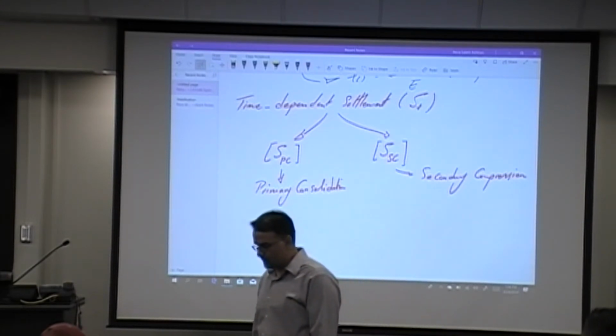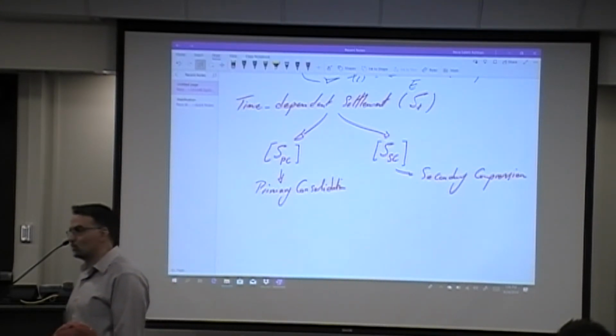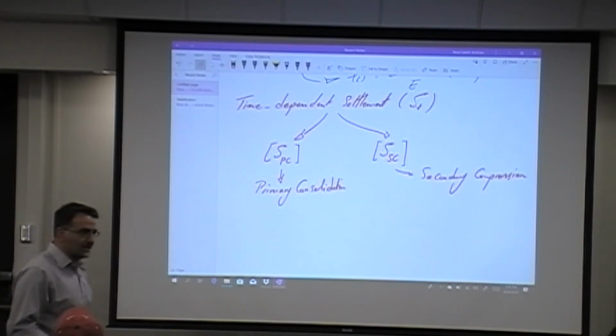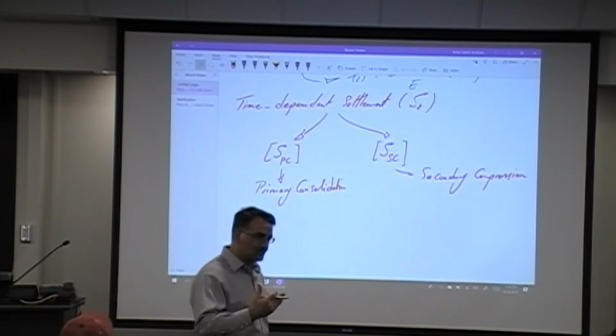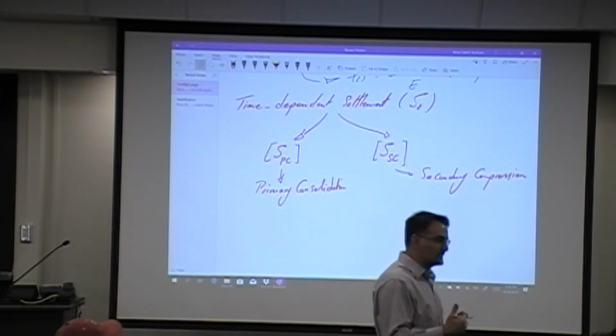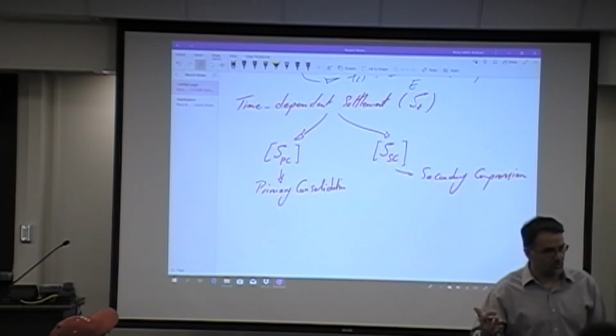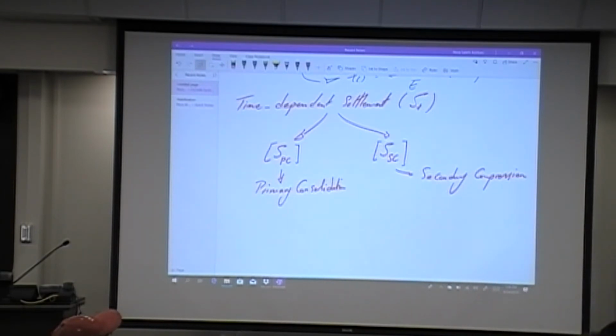Now we do have the second component that is called secondary compression. The secondary compression, still researchers debate what the purpose of that is. A lot of researchers will say that it has to do with the shifting and readjustment of the particles at constant stress, which is similar to the creep behavior of the concrete that you're familiar with. Right? So this has to do with shifting and readjustment of the particle at constant stresses.